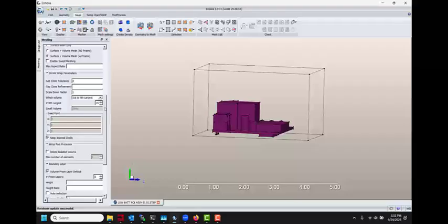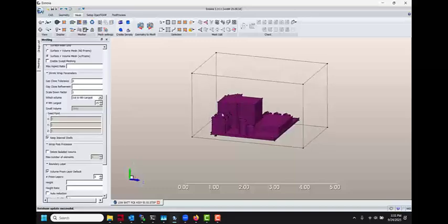Those are the big ones that are going to cause the airflow, the heat sinks and bits and pieces. So I'm just going to look for 15. If you want to look for all 30, that's fine. But for this test, I'm just going to look for the top 15. And I'm going to look for closed volumes. I'm going to assume there are no paper-thin shells anywhere, so we can turn it off.